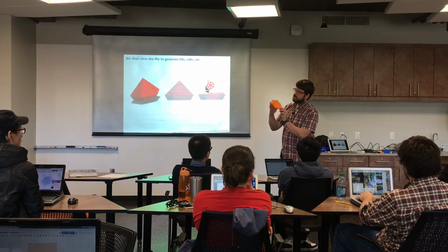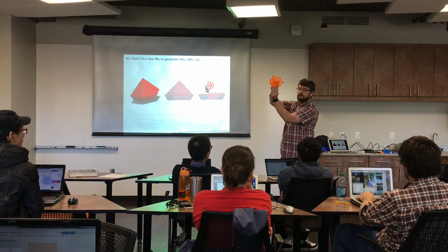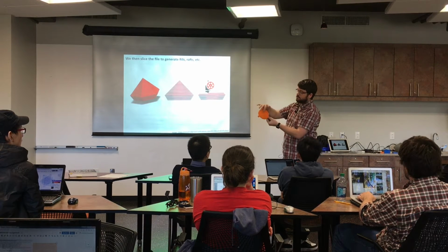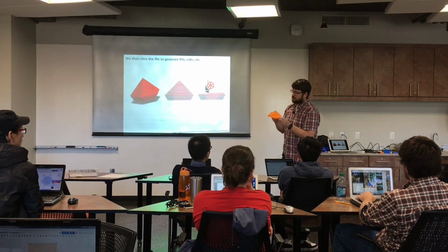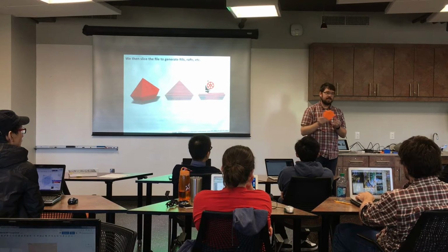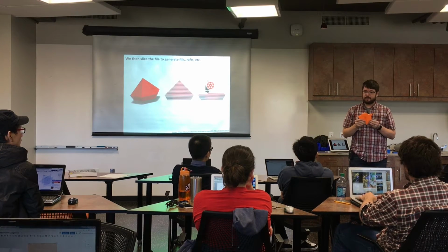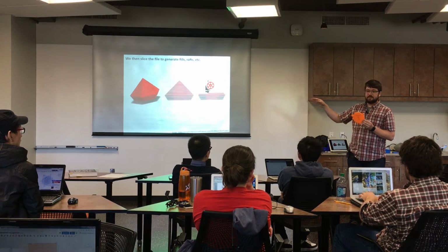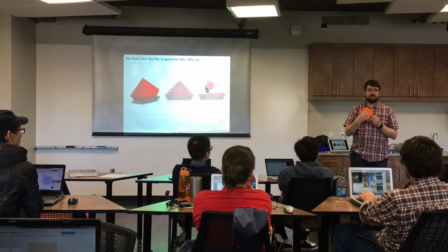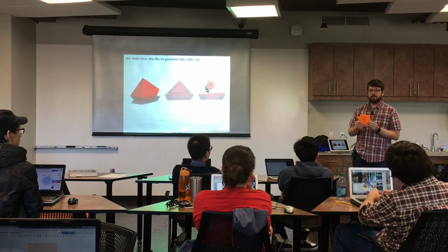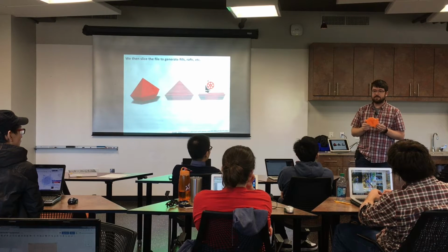So for example, if you look through, you can see the support material for these pockets in the top. But this saves a lot of time on your print. It saves a lot of plastic. It makes the part pretty strong, really. And that's all done by the slicer. So you don't model all of this in your CAD tool. The slicer takes care of that for you and takes care of generating any support that's needed.